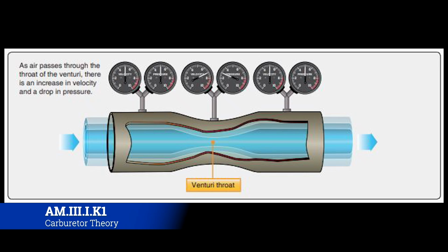Okay, the heart of every carburetor is essentially the venturi. What the venturi is, if you remember back from General, is simply a neck-down tube, for lack of better terms. It's taking the same volume of air that's moving at a certain velocity, and it's causing it to get squeezed and therefore go faster. As it goes faster, it will exit the venturi and start to expand.